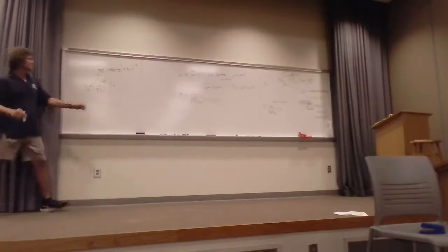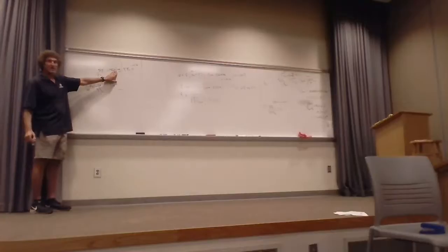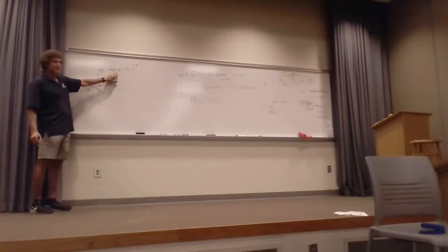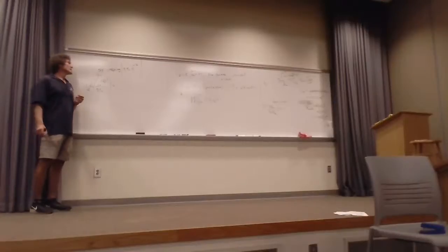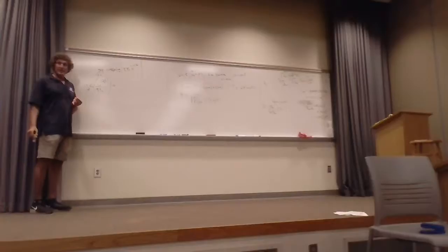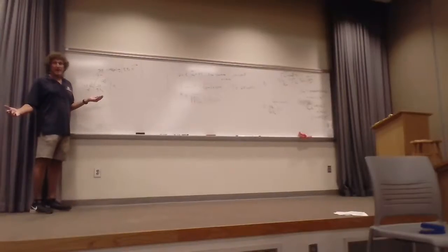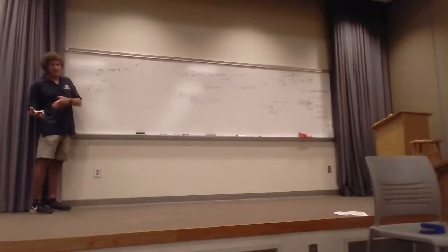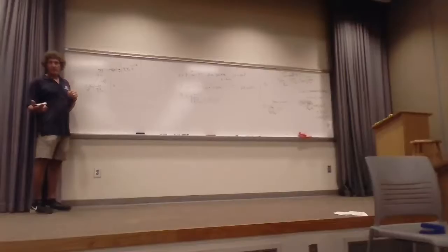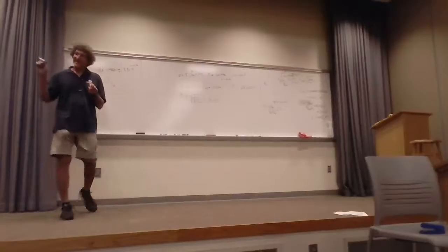The only thing I'm doing is solving this equation right here that I had, minus 20 times the log of tau 1, tau 2, e to the minus alpha z, for z. You follow me on this, guys? All right, it's just an inverse problem. I give you the shielding effectiveness, you tell me the thickness. One gives the other. They're linked.